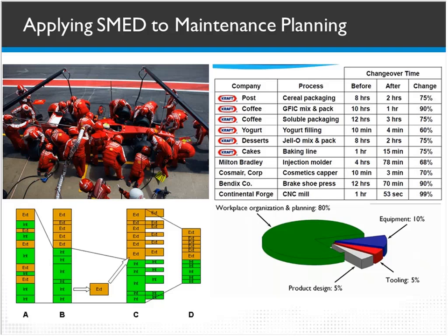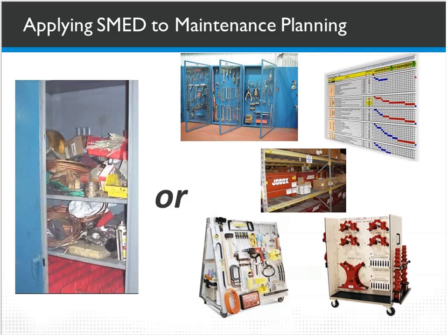Very little comes from special tools or special equipment, but there's so much impact that we can make if we applied SMED-type principles and moved the green internal activities, changing as many of those as we can to external, which means we do those before the maintenance event, before the down day comes along. This is our prep work that is going to reduce the overall time of the maintenance scenario,